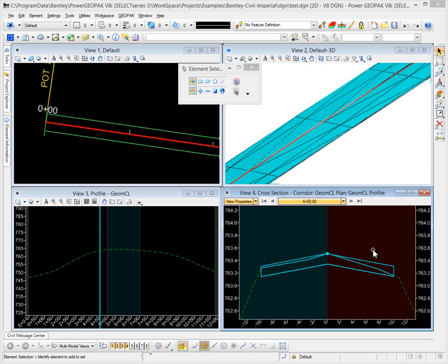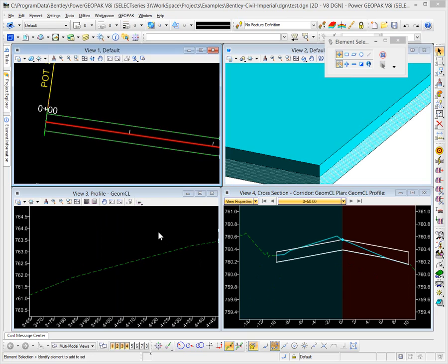And so that concludes the 4 examples in terms of how we can come up with different scenarios with our overlay. The next thing we want to take a look at is how the optimization of the profiles takes place on these particular examples. So using our template that consists of 2 components, one for crown correction milling and the other for the leveling binder that goes to the bottom of the milling and then follows the component along the top, let's look at now adjusting the profile to optimize different design scenarios.